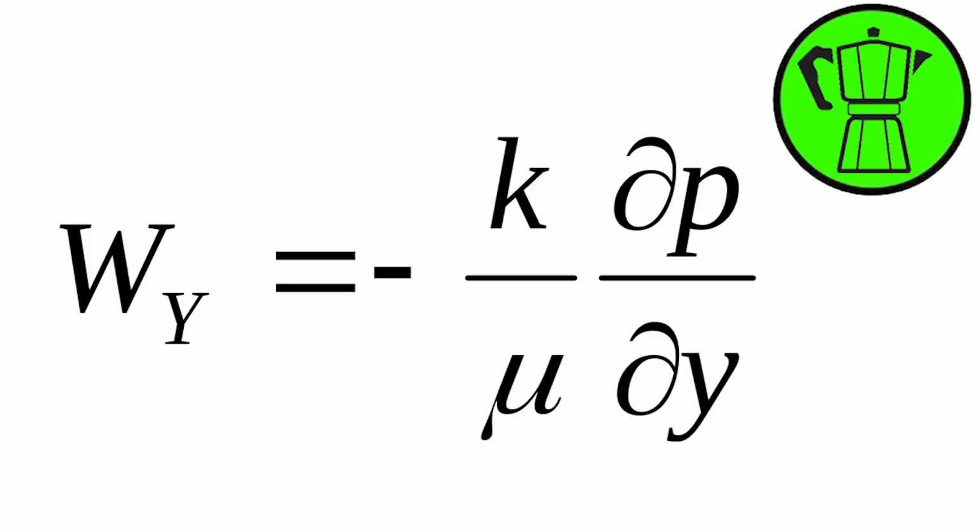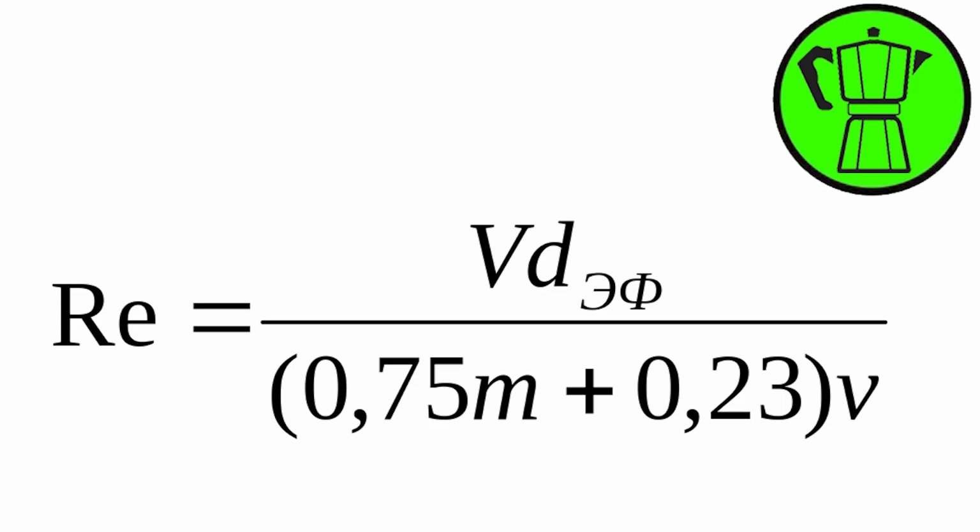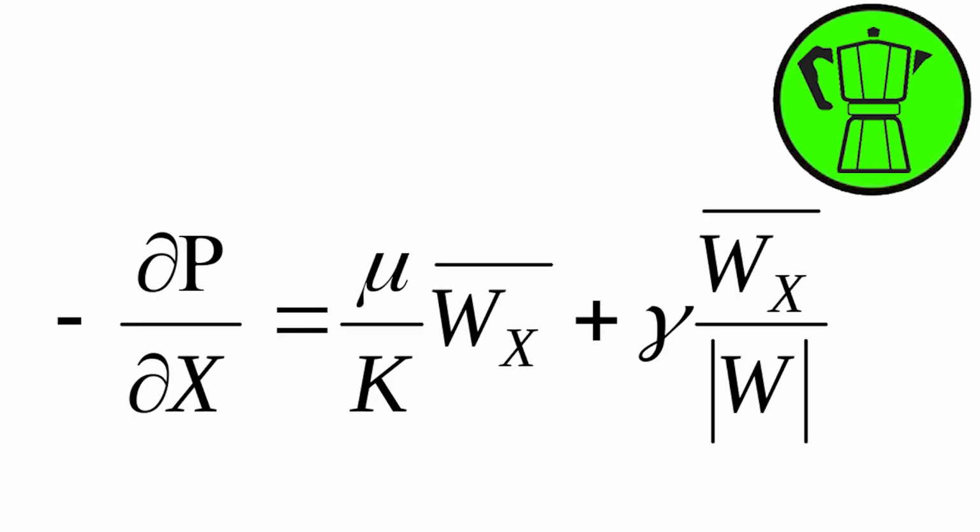In other words, this law determines how fast a fluid moves through a porous medium, depending on the pressure gradient and the characteristics of the fluid itself. Darcy's law is important in hydrogeology, oil and gas, and other industries, where it is important to understand and predict the movement of fluids through porous media for exploration, production, or storage of liquid resources.